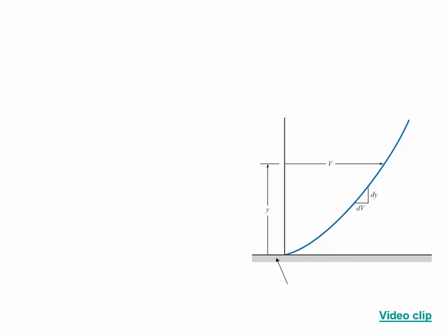So that's what we're looking at here, a cross-section of the water flowing from left to right. This is what's called a velocity profile, or a velocity distribution. And what it's showing is that when the water is touching the soil at the bottom, it has 0 velocity. The water's going the same speed as the solid that it's touching. But then the further away you get from that surface that's applying resistance, this frictional surface, the faster the velocity is. And so here we have dv, which is increase in velocity. So that is this horizontal component. The further away from this axis we get indicates a higher velocity.